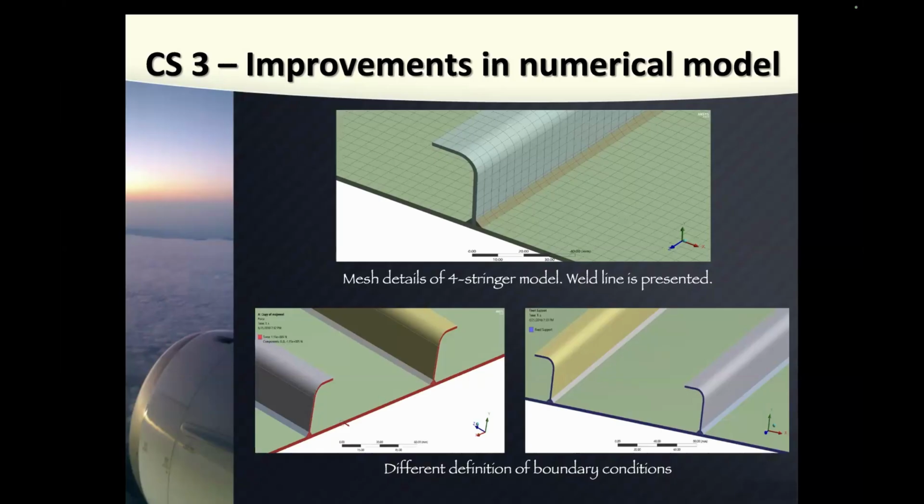What was wrong, briefly, in their calculations? They didn't calculate well the range of K, the stress intensity factor, even though they have all the data from the experiment. Basically, in an experiment, when you deal with dynamic load, you are trying to keep the maximum and minimum load fixed. For example, 180,000 newtons is the maximum value, and if you want to keep a ratio of 10%, then 18,000 is the minimum value.